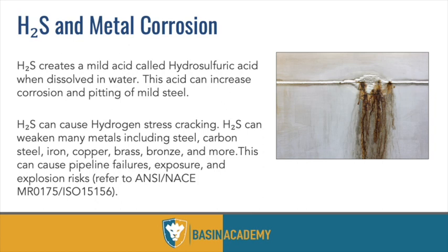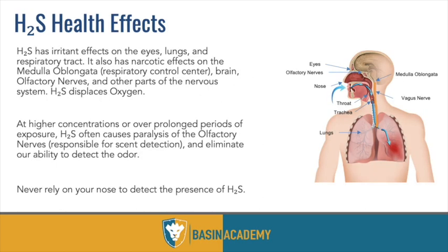wells have a tendency to become sour over time. So they may not be sour, or over, essentially, 8 parts per million in the stream for a long time, and then all of a sudden, boom, it'll happen, either through communication with other zones during a frac. It can kind of break up the zone and move an H2S area into another well. Improper treatment, if we're putting water down hole where organic material will break down and then release sulfur, and then the hydrogen that's in the water and oil and the sulfur from the organic material that's breaking down will bond and create H2S. So untreated waters, a lot of different things can turn a non-sour well into a sour well.